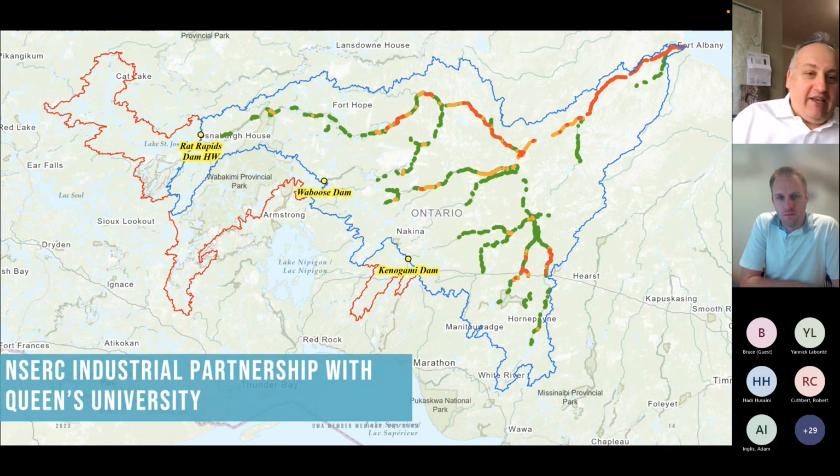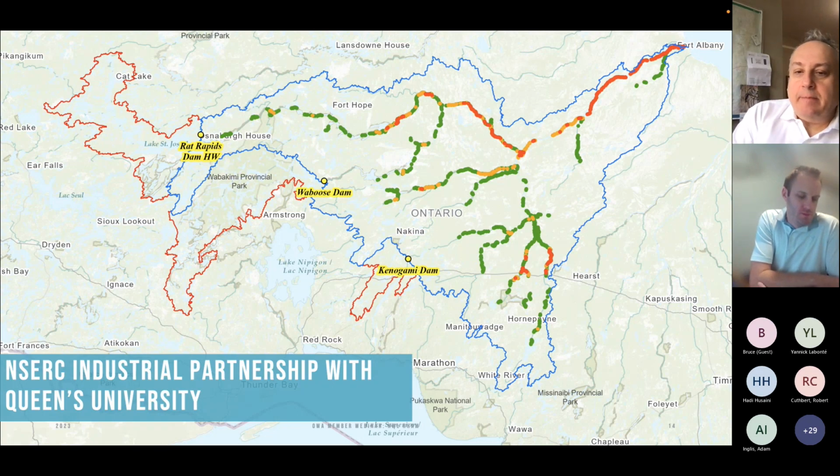When we first did the study in BC, for example, we found all of this hydro potential on the Columbia River between Revelstoke and Mica, and we realized that the digital elevation model was pre-1983, when the impoundment of the reservoir for the Revelstoke Dam started. So one of the things in our quality assurance, quality control process is making sure that the results are reliable considering the vintage of the data.